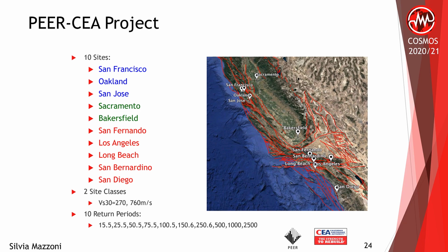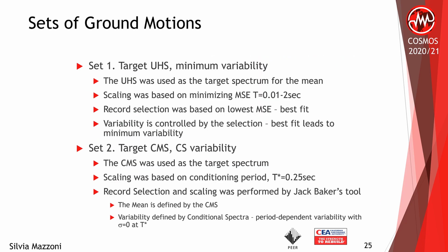We just got a report out on this. We were looking at 10 sites, and we needed to develop ground motions for fragility curves, so we had to do this for several periods. And so it's neat because it gives you a really nice suite of ground motions.